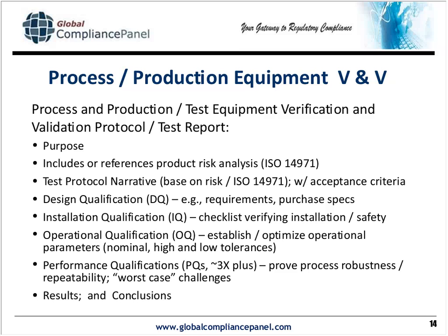Operational qualification, to me, is the point where you optimize or establish your parameters. I use, in some cases, a design of experiments to do that. Many companies just take what the sales rep gives them or what they've used on similar pieces of equipment. I've seen that even on some of the forums, even for validation. We don't need to validate, it's the same equipment as the previous one we bought. I would totally disagree with that. You may reduce it, but there's no such thing as two identical pieces of equipment, even if they're the next serial number off the production line from the manufacturer supplying that equipment.